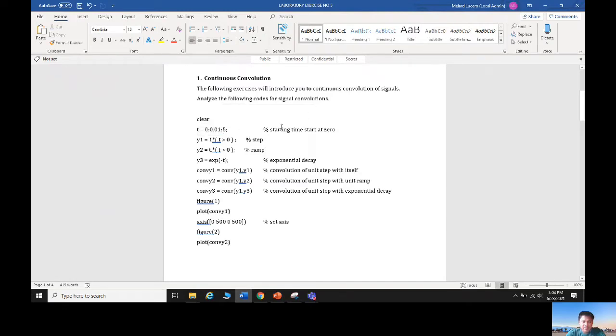This will be the start time and the end time. So literally it is 0 : 0.01 : 5. Basically this will be the start, then the end will be 5 in terms of seconds. The variations will be in steps of 0.01. By this, we can see that in 0 to 1 second, there will be 100 variations because of the 0.01.